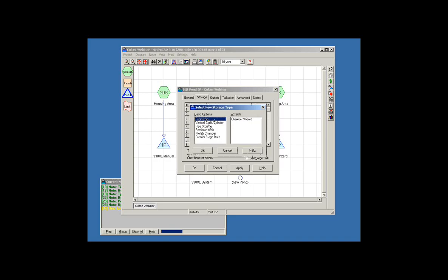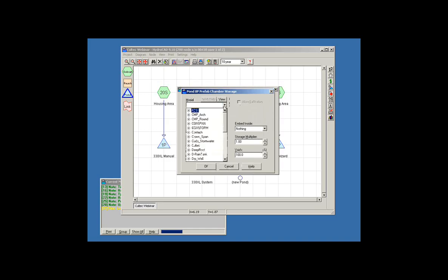Now I mentioned that the V8 has slightly different length start and end units, so we need to put in one more storage definition here, which is again going to be a prefab chamber. And we're going to come down the list here, and pick the CULTEC V8 start and end unit right here. And we're going to set our invert elevation again for 100.5. And we need to specify that we have 8 of these chambers. So in this scenario, we've got 4 rows, and we have a start and end unit on the end of each row, so a total of 8. And we need to embed these again in our stone field.